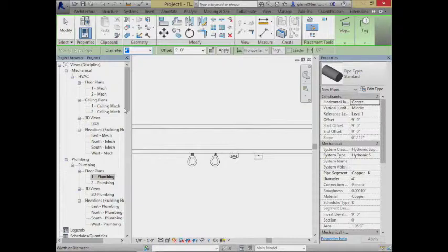You have the issue of the offset, and that is the offset relative to Level 1. So here's how this works. If Level 1 is right here, or wherever the floor level happens to be, when you're running a lateral pipe for the sewage, they tend to be fairly low to the floor, or even below the floor, because they have to be lower than the toilets. Things don't like to go uphill. So we have to have it start fairly low to the floor, or even be below the floor in the ceiling plane of the floor below. Either one of those will work.